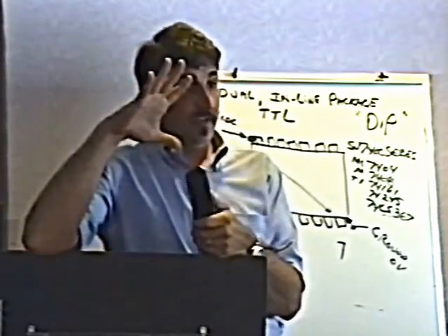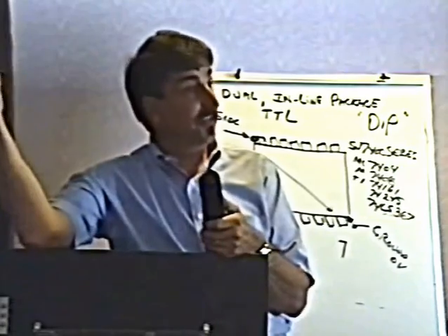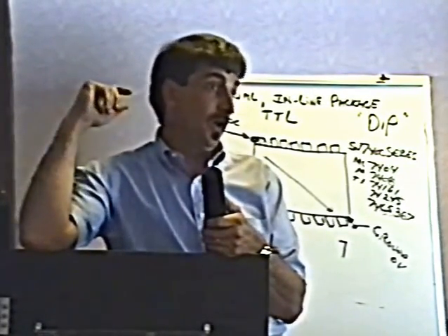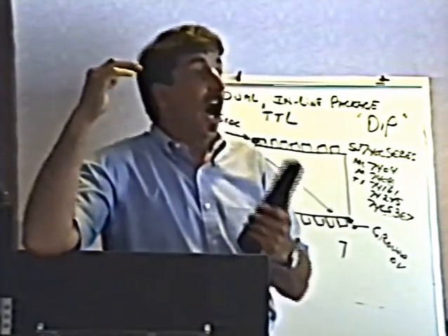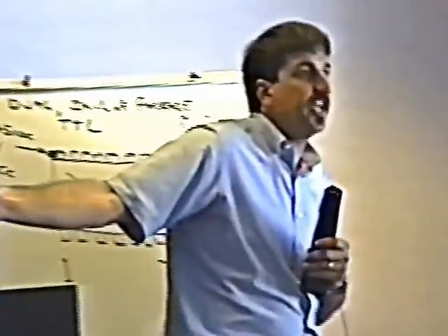It's real bright on one side and real dark on the other. It has a typical capacitor failure. It happens to be capacitor C702. And I know, like I said, I'm not a genius. I see this 100 times. I've changed C702 in 100 different monitors.